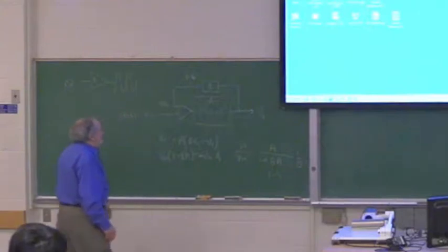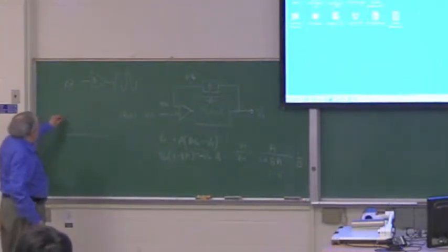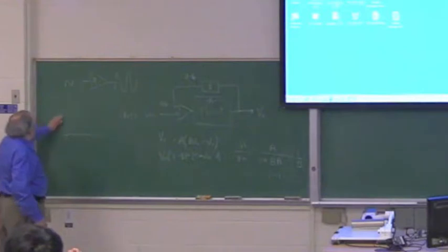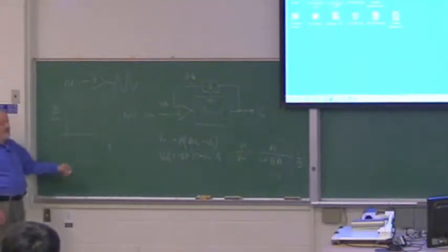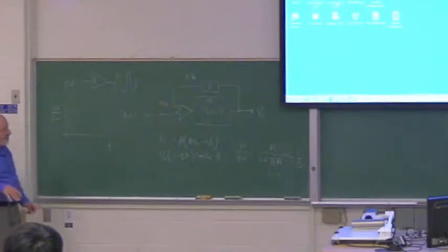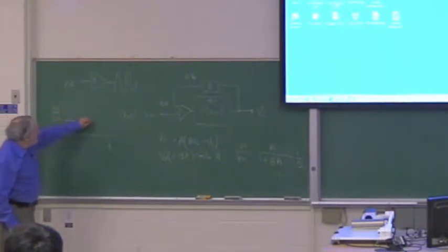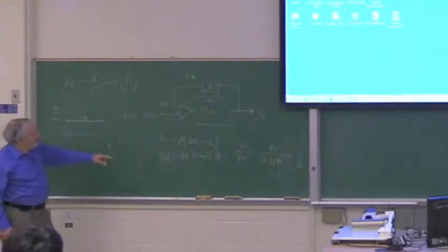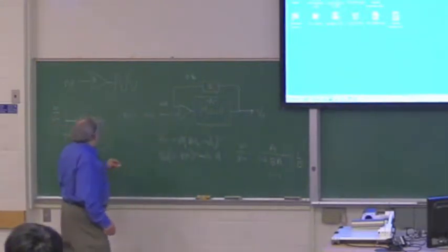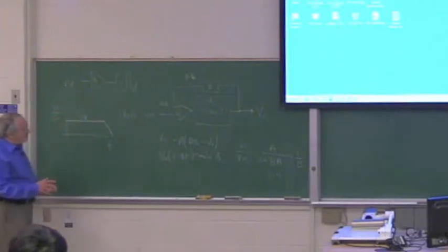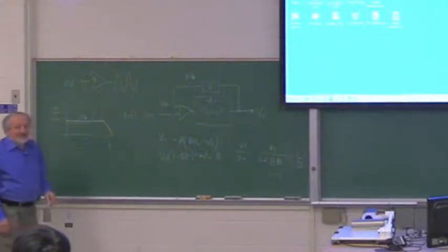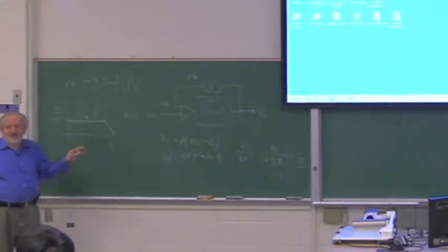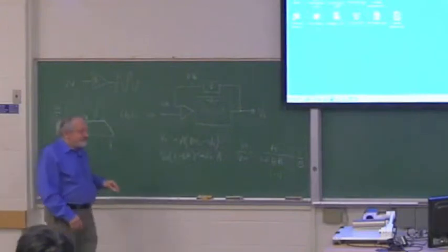So normally, if you do a transfer function, and again I'm sure you've seen it before, this is V out divided by V in over frequency, an open loop amplifier typically looks like this. At higher frequencies, the gain goes down. If you close the loop, you will get a constant gain, which equals 1 over B, as shown here. And at the end, it will just roll down. But if something goes wrong, if there is too much phase shift and so on, you'll get something strange like this, to the point where it wants to go to infinity. Is that clear? Good. Okay.